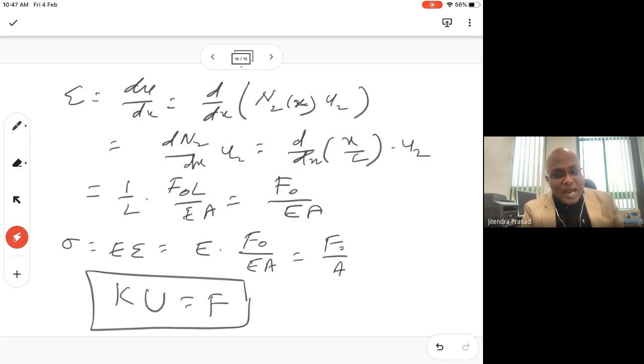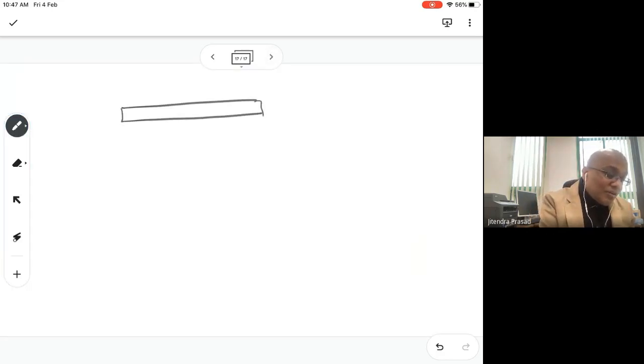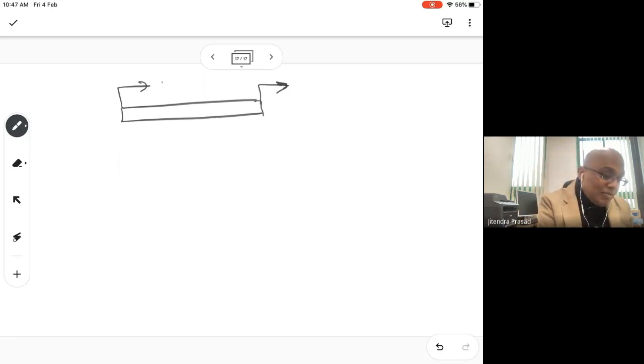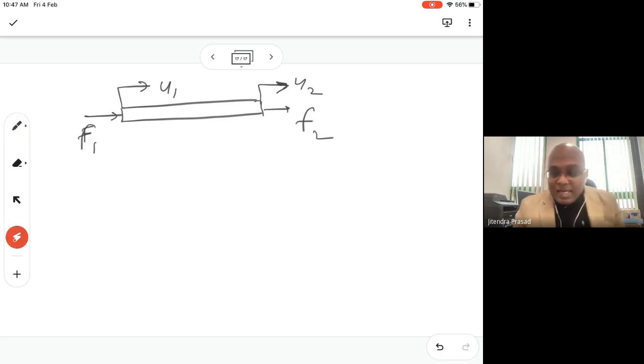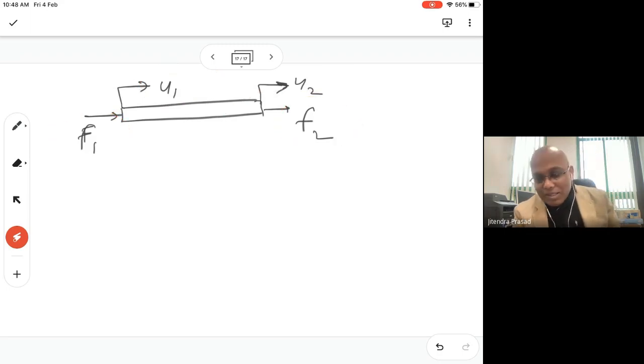In the trial function we are writing, we will assume, although we know that either this or that can be given, right? Either you give displacement or force, but we can do some general purpose formulation in which we can give this essential boundary condition, and at the same time we can also give a natural boundary condition as well, just to make it general purpose.